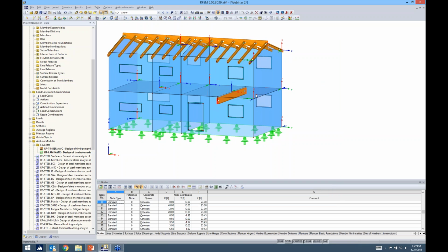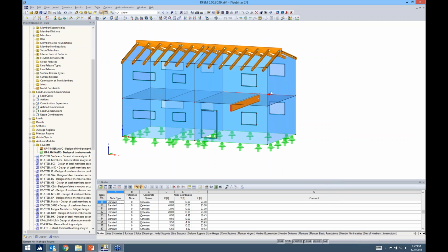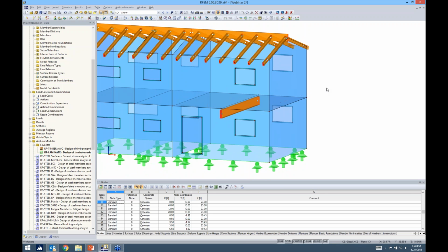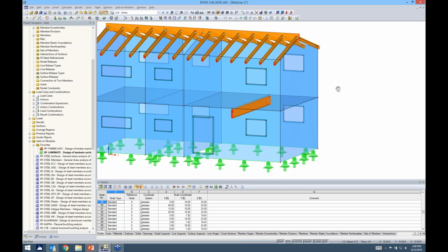Along with the orientation of the axes, you'll notice here that we have our walls framing into each other, and this is a rigid connection now. For cross-laminated timber, we probably won't have a rigid connection, almost guaranteed. So how do we address that? And the answer is with line hinges in the program. So every surface is just composed of line elements on the outside.